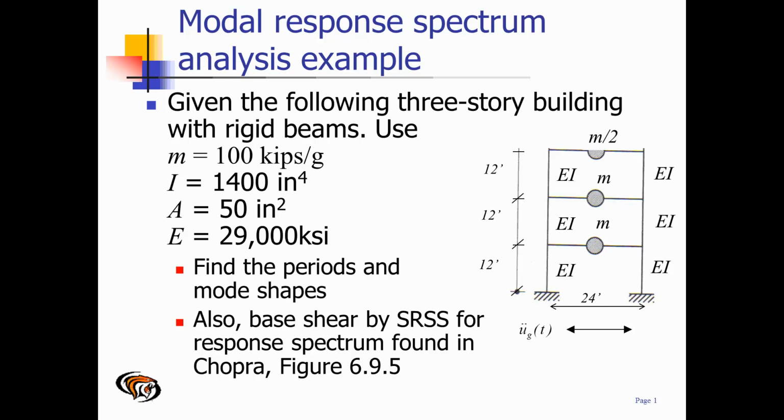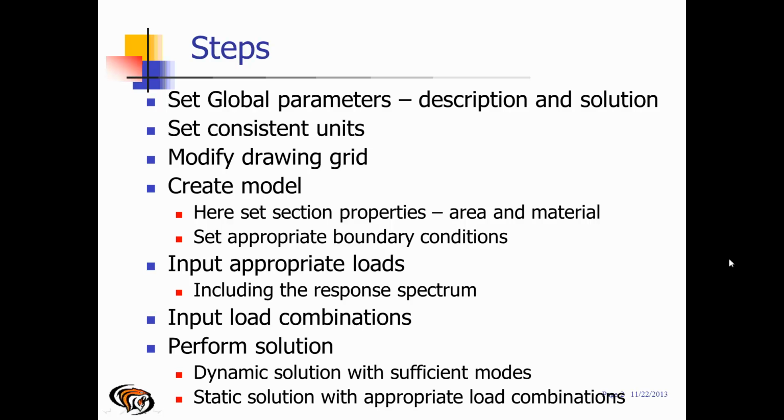We are solving first for the periods and the mode shapes, and then we will find the base shear by the square root of the sum of the squares for a response spectrum found in Chopra figure 6.9.5. The steps in RISA are as follows.